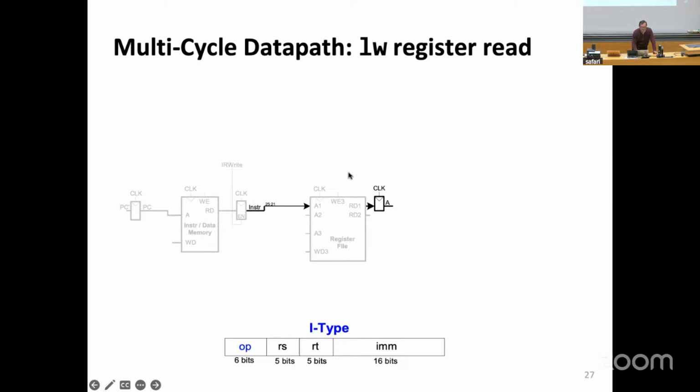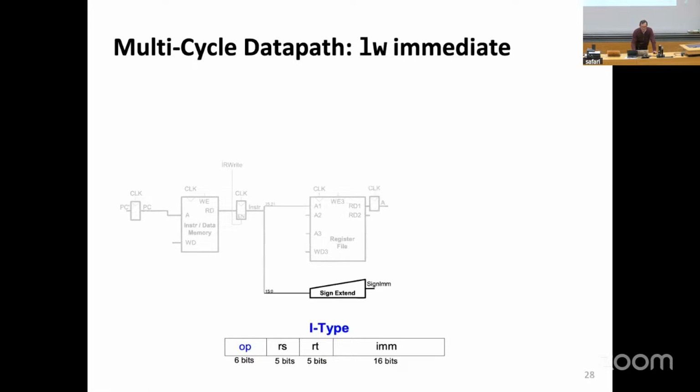This is register files automatically enabled. There's no write enable. You need to do no harm to the register file at this point when you're actually reading a register for load, etc. And of course, I'm not connecting other things that I don't need for now, but we're going to use them later on. Okay, so load word actually,